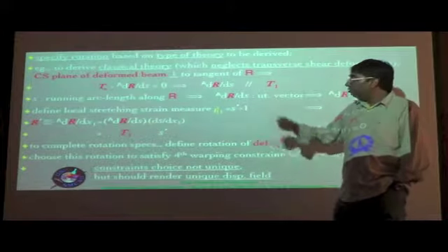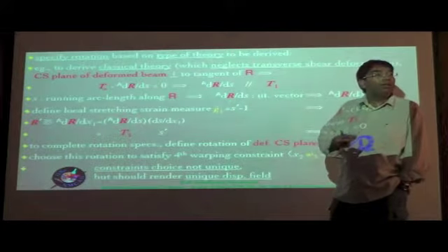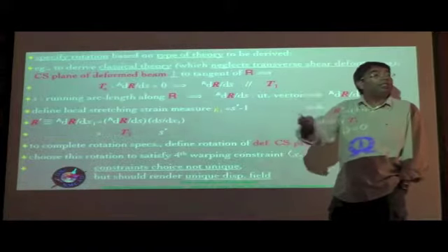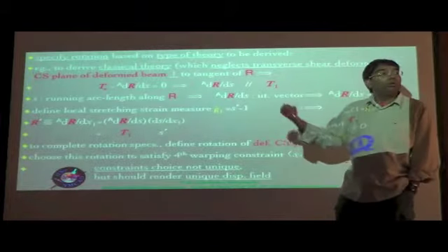So you cannot have constraints which still have some redundancy involved in there, or in other words, for example, constraints which are linearly dependent on each other, for example, would be a case where you would have not entirely removed all the 4 orders of redundancy that are involved. So your entire displacement field should be rendered unique by the choice of constraints, and this is the 4th constraint, which is one of those such choices which enables the redundancy to be entirely removed.